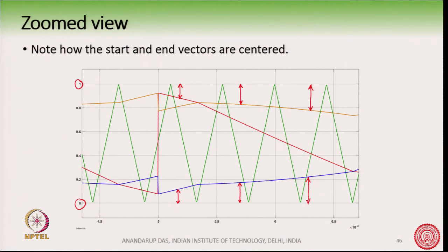So, this is the second offset. Note that the second offset is also a common mode voltage. It is added equally to all three reference waveforms, so that we are basically shifting up or down the whole set of three waveforms so that it becomes the middle of the span of 0 to 1. So, this is what we are doing.